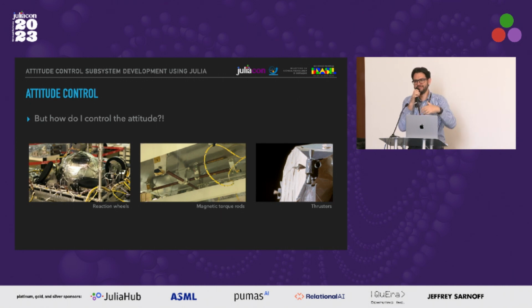But a magnetic torque rod is not that interesting because it's just a current. So you send it to both, to the simulator and to the actuator. But the reaction wheel is a bit more complicated, and we do this by reading the telemetry and feeding the simulator.